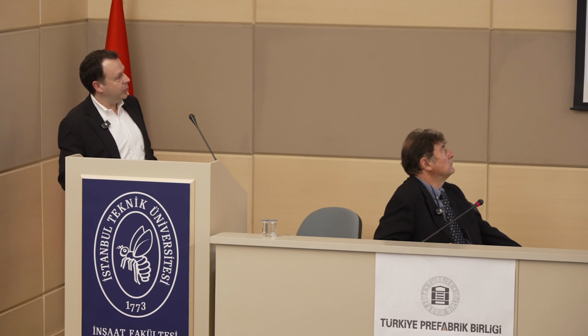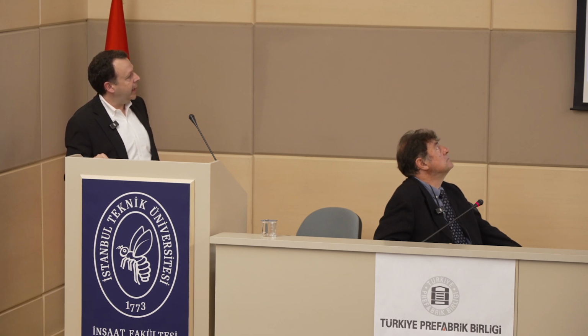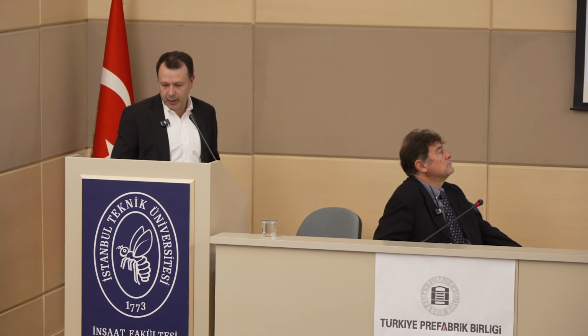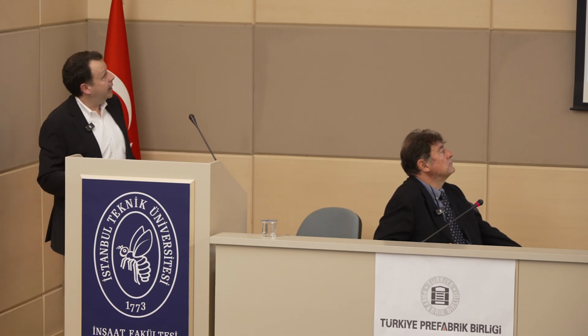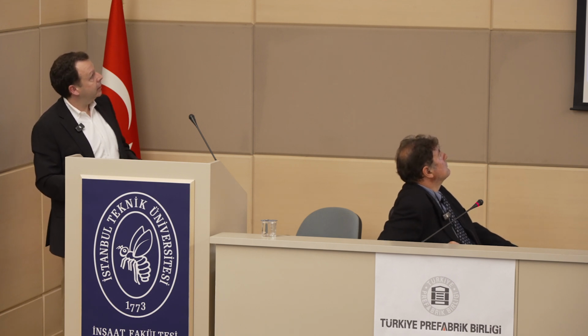The beam hinges were defined as moment M3 hinges, deformation controlled hinges in ETABS. Depending on the slightly different reinforcement, we have 3 different beams. Here are the parameters actually assigned in the code-based design versus the objective-based design.